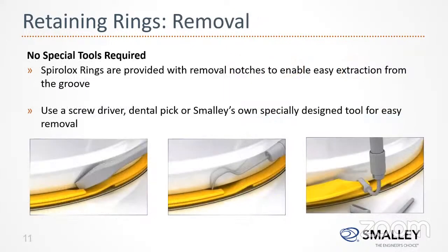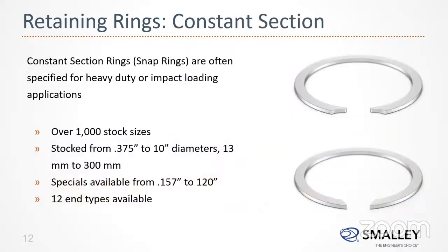So this is how it is removed. There is a small notch. The cut will be there. You can put a screwdriver or a small special tool, if required, and then just pull it and remove it. All the videos are available on our website, smalley.com. You can refer to them.